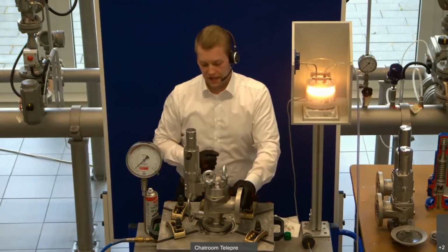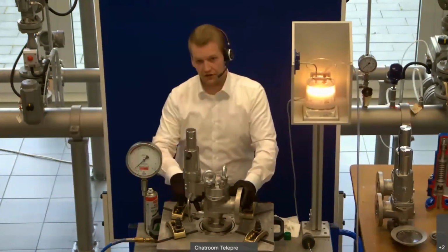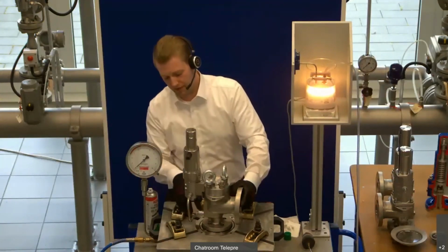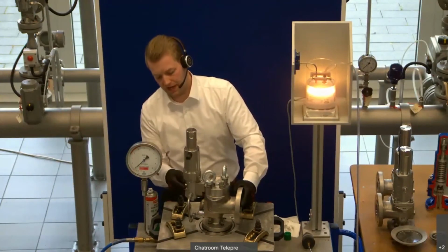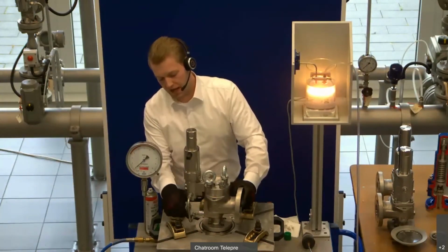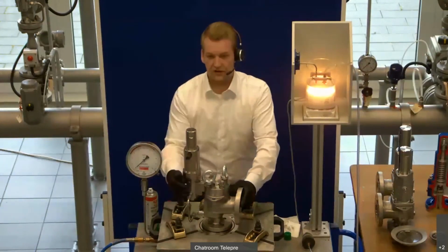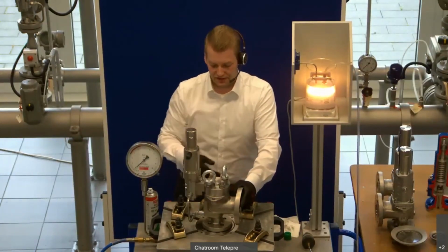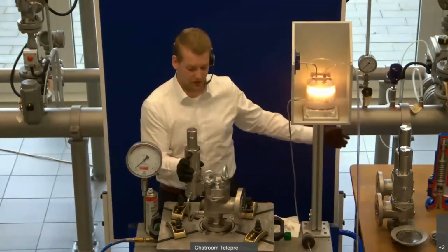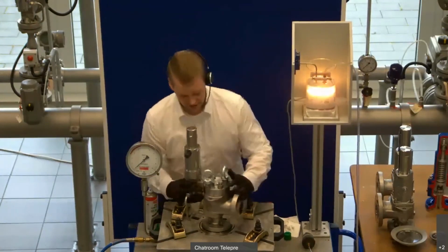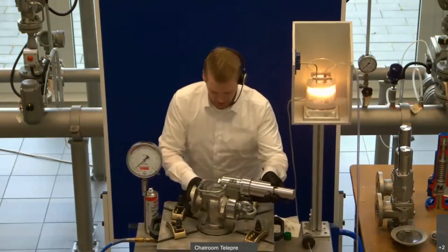And here is now important, there is a connection, the tubing from the inlet of the pilot operated safety valve to the pilot. And this tubing we have to spray with liquid spray and have a look if there are some bubbles or not. There is a difference to a spring-loaded safety valve, the API model before. And now there is the same method here. We're going directly to the outlet.